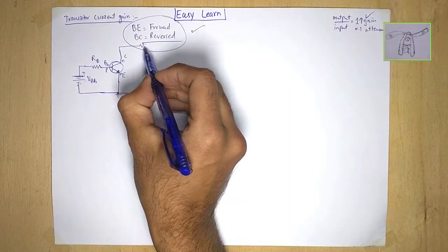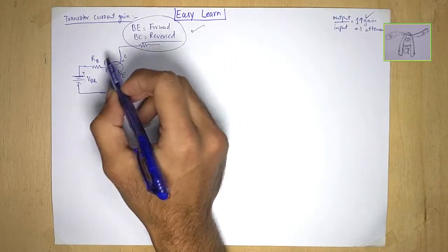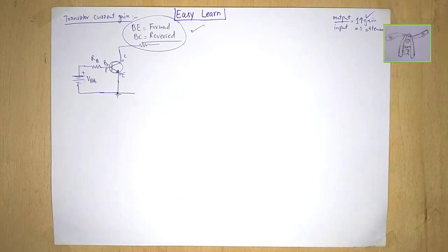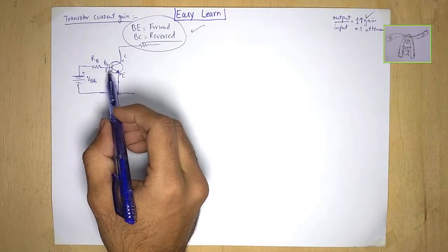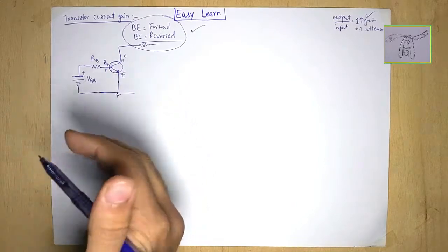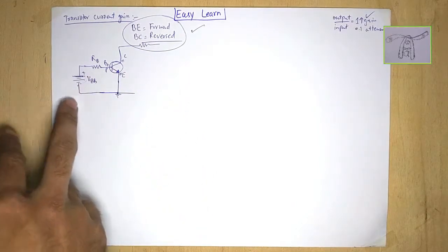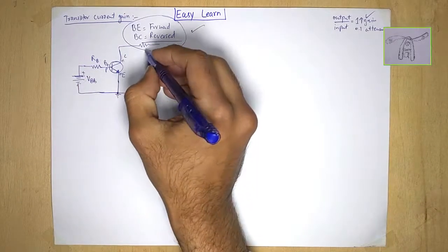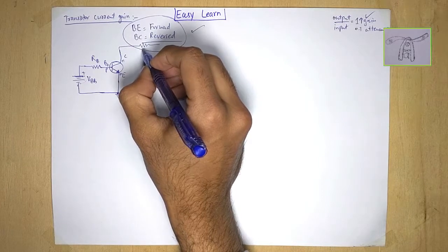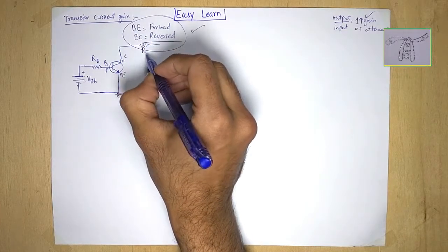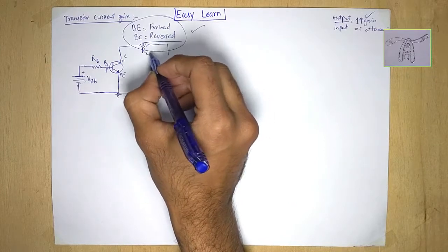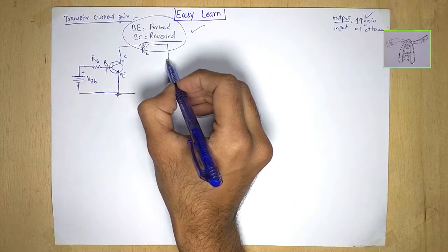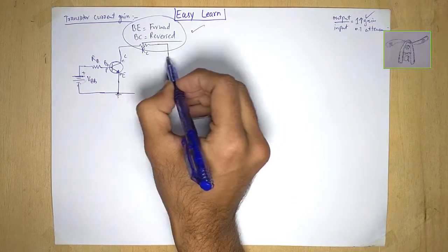And here is another resistance. These resistances are just for limiting purposes, and they have no other aspect here, just to protect our base collector junction and to set our outside polarities within the range of the ratings of the transistor, nothing else. And this resistance is at the point of the collector, so we can say that this is RC, which shows the resistance at the collector in series with the external source.